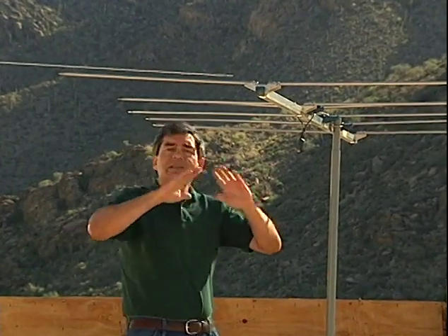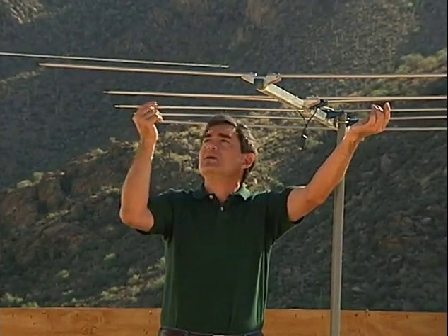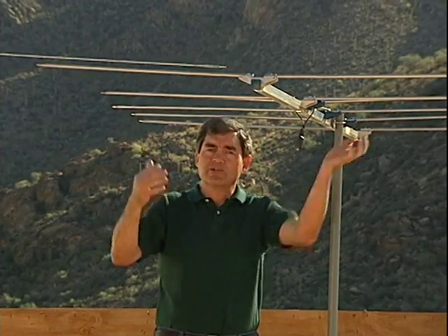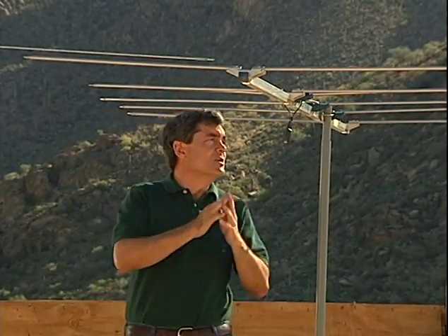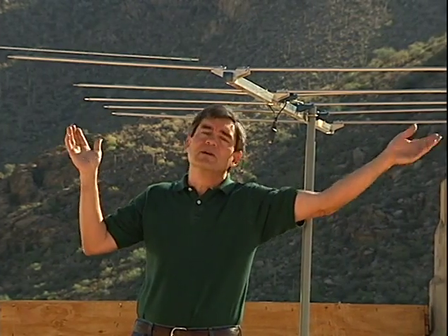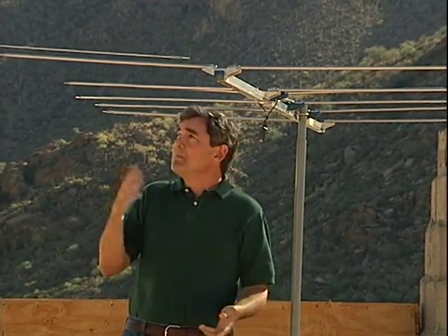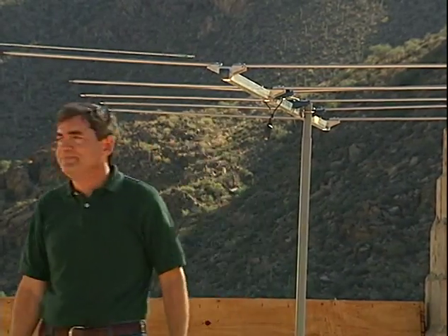Now, how well an antenna works is determined primarily by the amount of exposed metal elements to the arriving electromagnetic field. In general, the more area, the better. But antennas are typically designed so that the receiving elements are at least a half wavelength at the lowest operating frequency. At the low end of the VHF channels, this turns out to be 9 feet, and at the upper end of the UHF channels, this is only 7 inches. So most antennas are designed to be a compromise between the two.